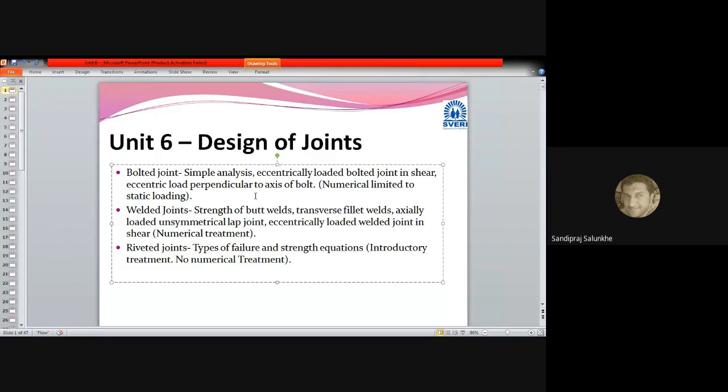These joints also form a connection, but it is a permanent joint, so we cannot call it a pair. The basic definition of a pair is that the connected parts have relative motion with each other. So these joints do not come under the category of pairs, and that is why we call them permanent joints.